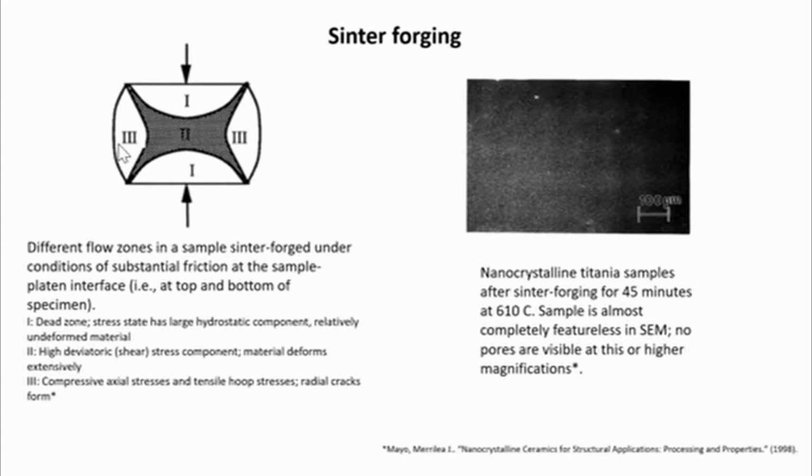The second mechanism of densification due to sinter forging is the closure of pores by plastic flow of the surrounding matrix. In this mechanism, matrix material is physically pushed into the pores to fill them, as the bulk material is deformed. By virtue of plastic deformation, a property unique to fine-grained ceramics, it is possible to close pores which are much larger than those that can be closed by diffusion.